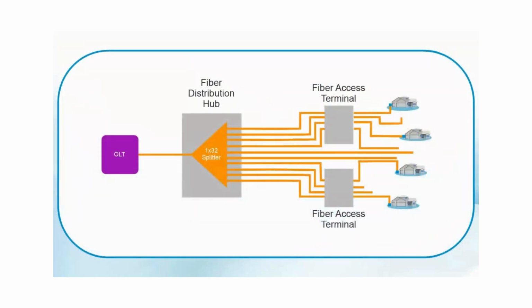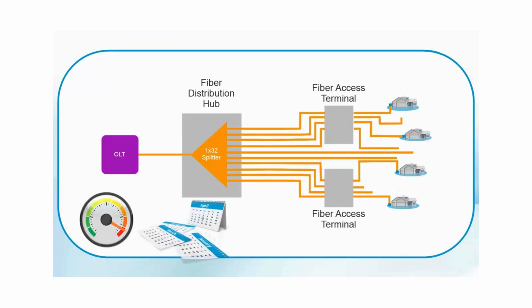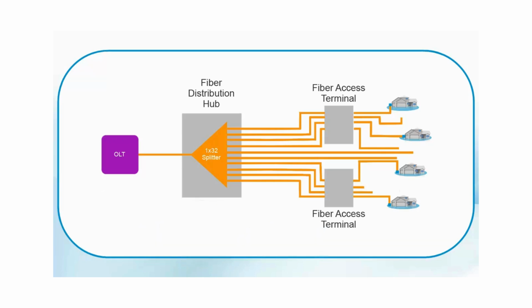A fully connectorized, centralized approach using an FDH offers some attractive benefits: speed of deployment, maximum long-term flexibility, and future-proofing aspects. Maximizing the use of connectors instead of splices whenever it makes sense enhances the accessibility of the network. One ideal area for a centralized approach is where take rates are not guaranteed, but may increase steadily as the area is further developed over time.